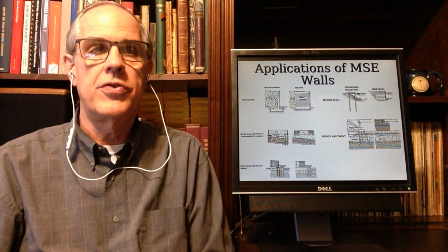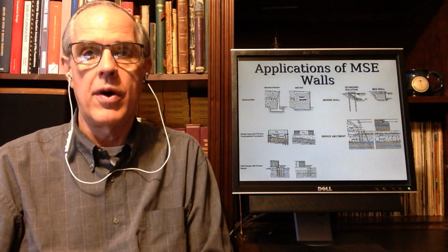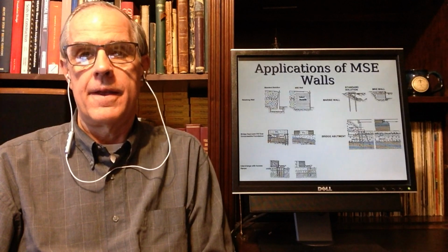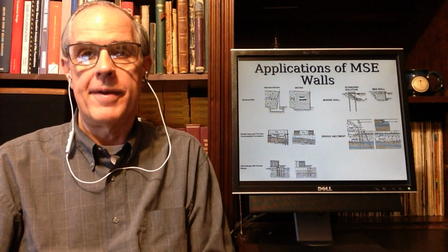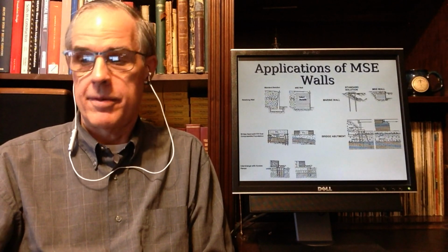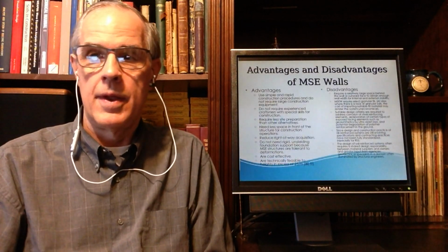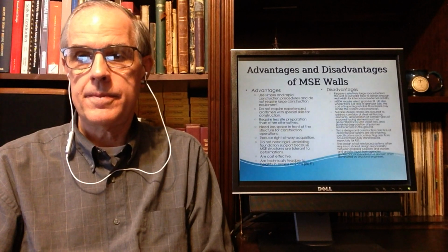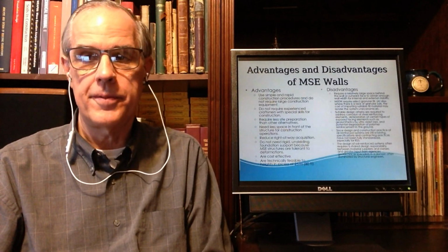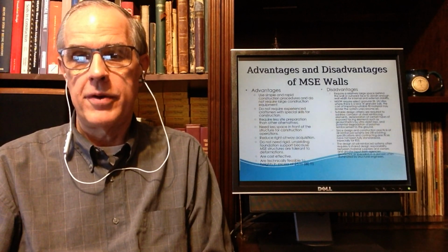They're very useful for where you need a very tall wall, and you basically have to build the whole thing up. So they can be very high. Advantages. They're simple, they're easy to construct, they can be done with regular construction equipment. They don't require experienced craftsmen.